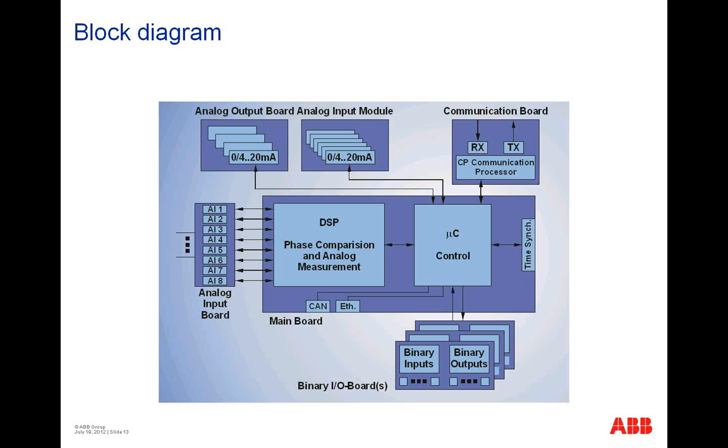If we would do it in another way, that means we get the initiation signal, then we take all these measurements, calculate, and get a result, we're losing time. And to avoid losing time, we do it all the day, all the time, every second: take all the measurements, make a calculation, and have a result. That means a result is always known for the network conditions. And if the initiation signal comes, the device can act directly without losing any time.